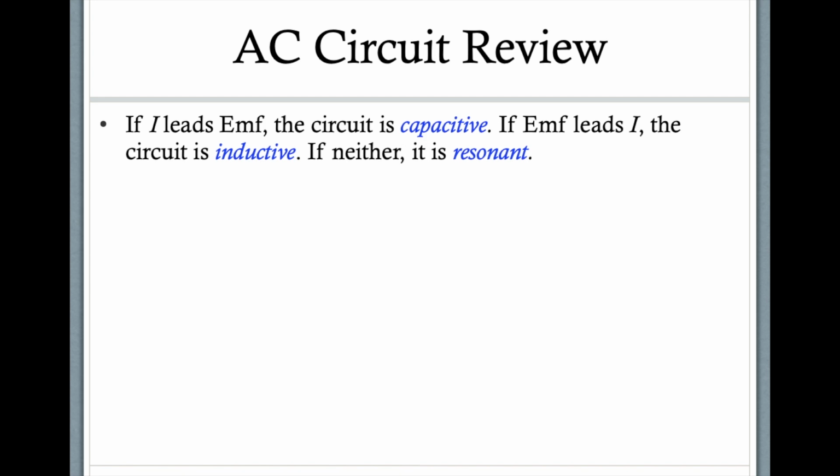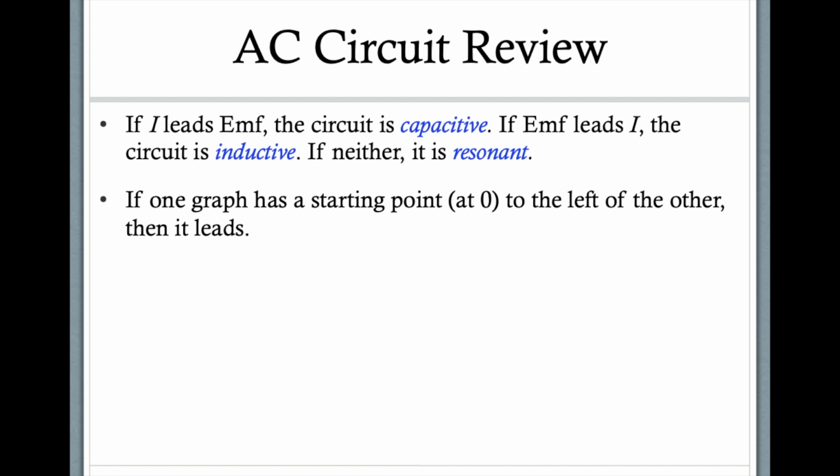If I leads the EMF, the circuit is capacitive. If the EMF leads the current, then the circuit is inductive. If neither, it is resonant. What it means to have one thing lead another is that if we take the sine curves and draw them to their very beginning, the one that is leading is the one that has the leftmost start.